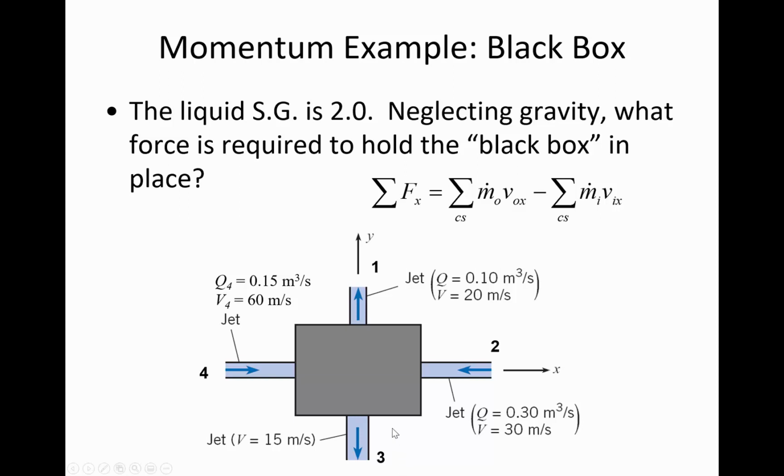So in other words, I said in the chat box, m dot 3 equals m dot 2 plus m dot 4 minus m dot 1. The other way to say that is the water that's going out at 3 is whatever water came in minus the water that went out at 1. If it goes out through stream 1, it's not going to be exiting at 3. But anything that came in has to go out, so it's either going out through 1 or through 3. And we already know how much is going through 1. So the remainder goes through stream 3.